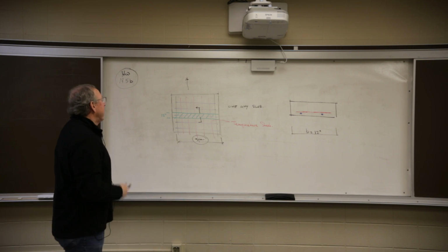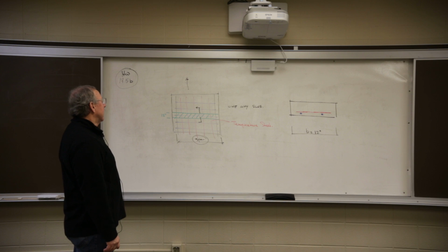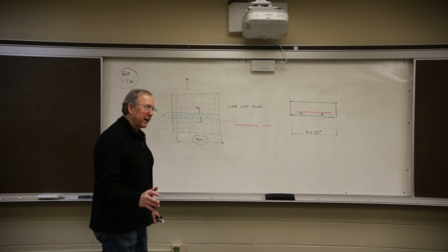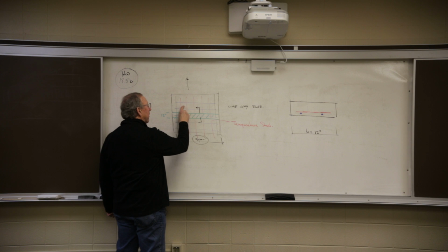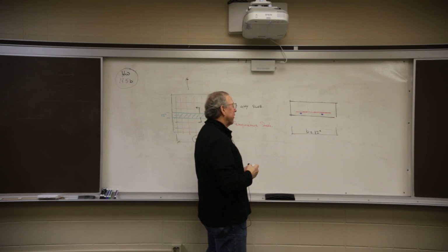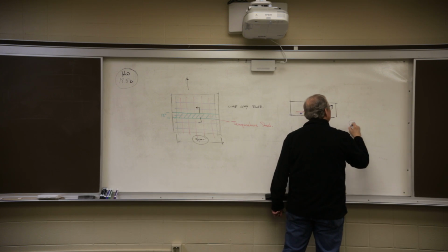So I've got main steel going the width. I've got the temperature steel going the length, and it ends up that I've got to design these guys, and these are going to be at some pitch. You can see I've got them drawn kind of apart. So when we get done, both of these are going to have a bar size at some pitch.